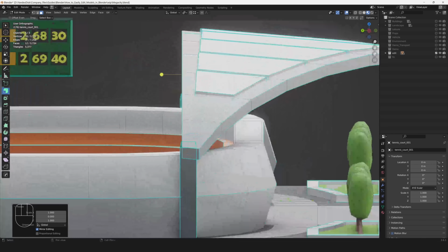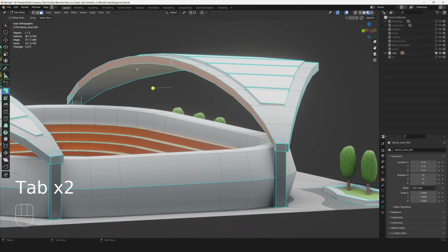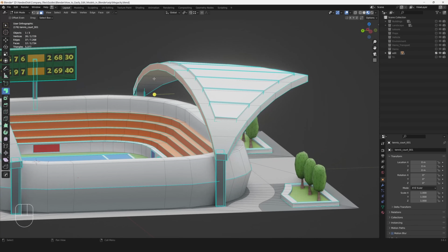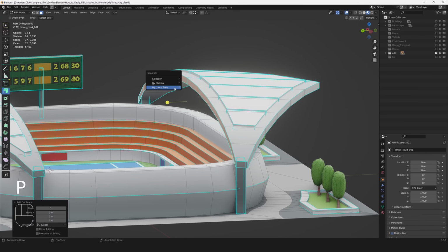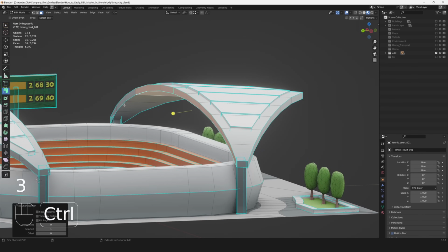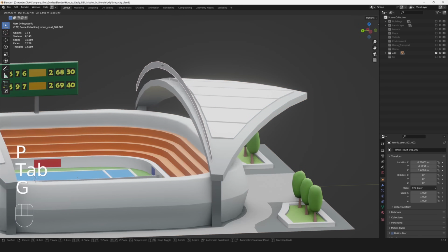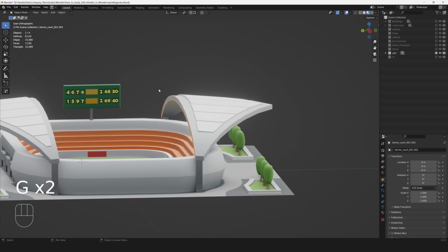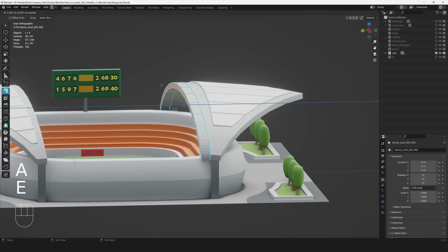To avoid intersections with this holder stick, we should place this a little bit further away. Now I should copy these polygons and separate them to a different object. To create copy quickly, I will use Shift plus D and then right mouse button click to make it in the same location. It's there, let's make sure that it is there. Let's separate it to a different object. Now we should extrude this piece of plane. Let's go to edit mode, press A. You can see we can extrude it, but we should extrude it only on one unit. So let's press 1.